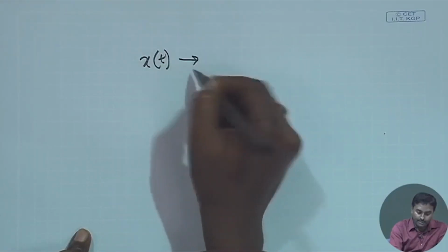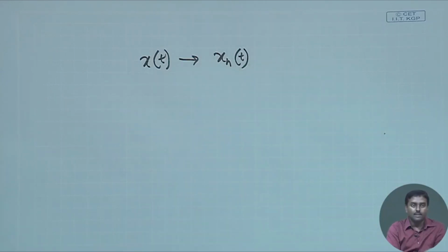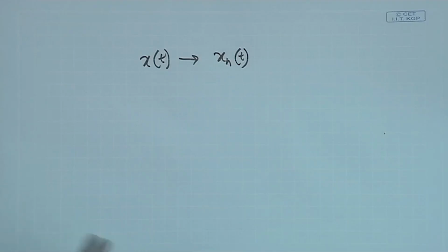Therefore, if you wish to employ a circuitry which does this transformation, all we have to understand is that to do this I have to take every frequency component and give a phase shift of pi by 2. So the original delay element will not do that, you have to selectively take, maybe with a very narrow band pass filter, every frequency element, and for everybody you have to give a pi by 2 phase shift. So that is what you will have to do. Generally it is a difficult circuit to realize.